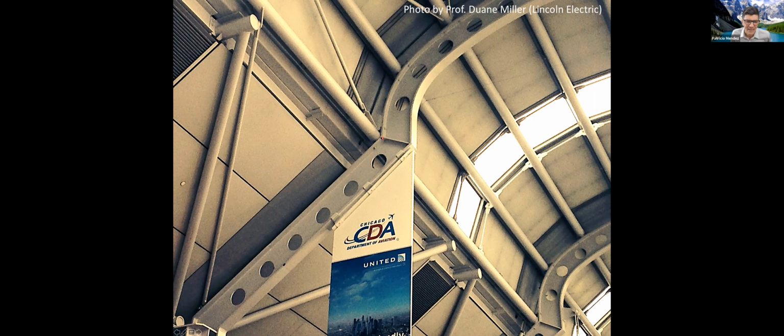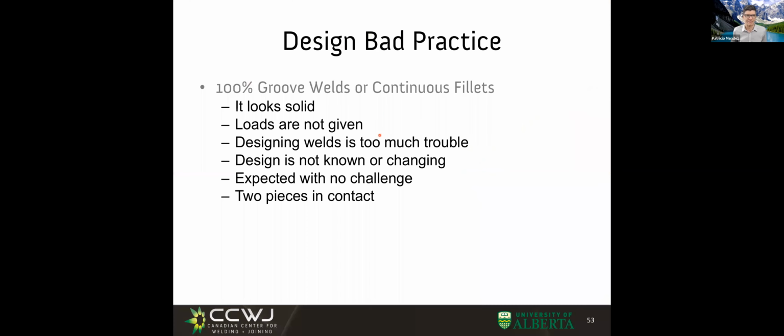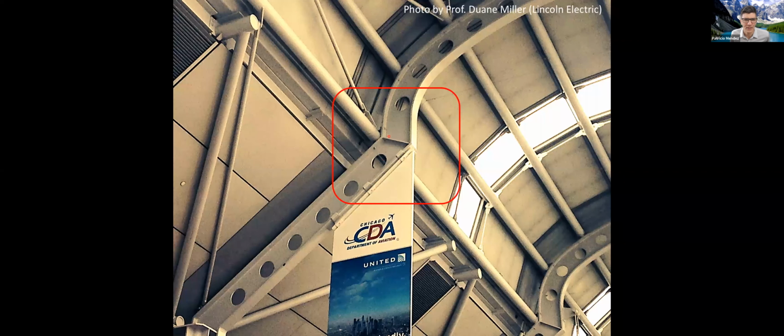Look at this. In this case, they welded a stiffener plate. Isn't this amazing? You know exactly why they put this plate here. And it's not obvious at all what load is being transferred. But now you know that what this plate is doing is preventing the flange from bending inside or outside, depending on the direction of the moment. Isn't this awesome? You're going to look at welds now, and you'll think, oh, I know why this happens. So this is this third principle. I think it's really amazing that we get to see these things.